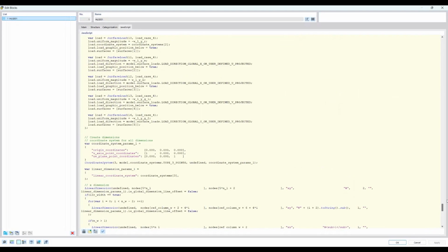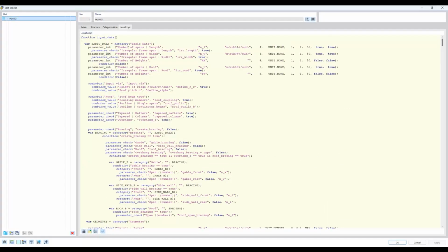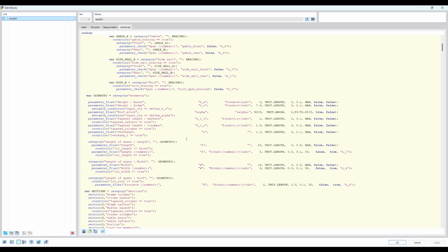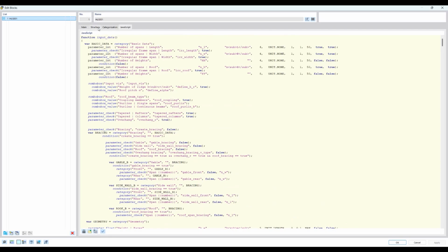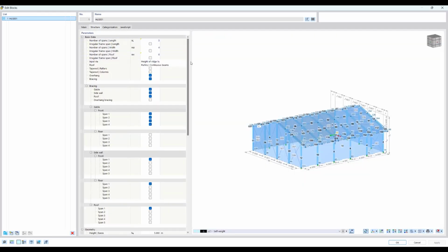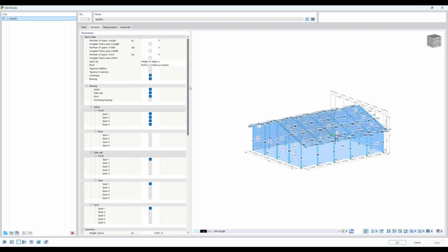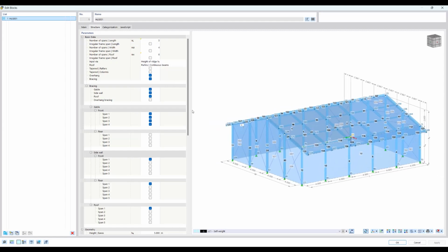So as you can see here, the whole steel hall is defined with these functions and API calls. Based on the structure here, you also define a parameter structure, and depending on what you are programming for the block, you now have your own input fields you use in your program. And this enables you to work with more complex structures.